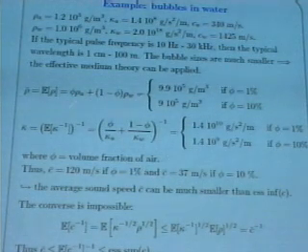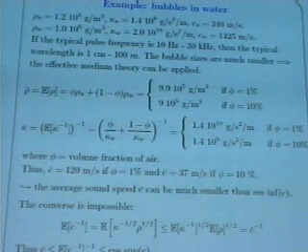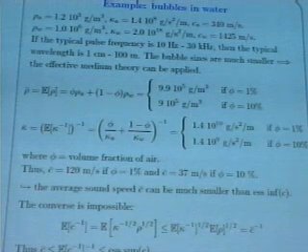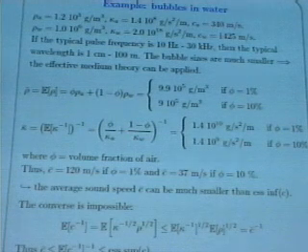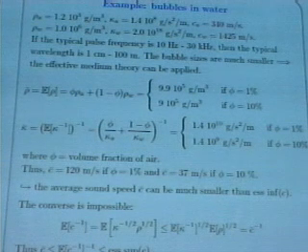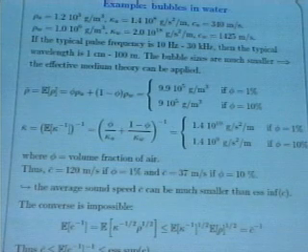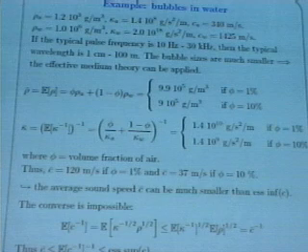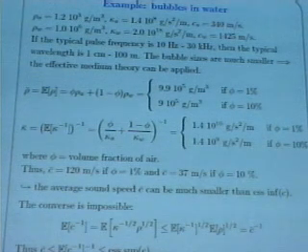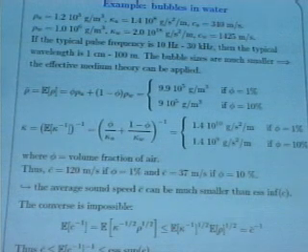So here I've just done this computation. Very, very simply, you can do it. And you get this very surprising result that the sound velocity in a composite medium can be much lower than the sound velocities of the components of the medium. And this holds true not only in acoustics, but in elasticity, in various other fields. And this tells you that composite media can have properties which are completely different from the elementary properties of the elements of this composite media. You can generate media with very strange, very fancy properties just by doing these simple computations.